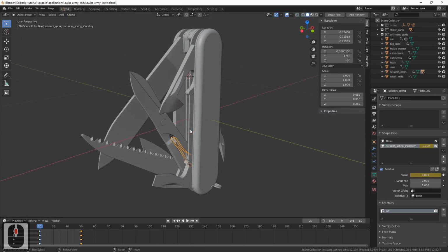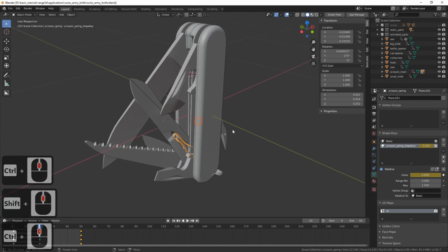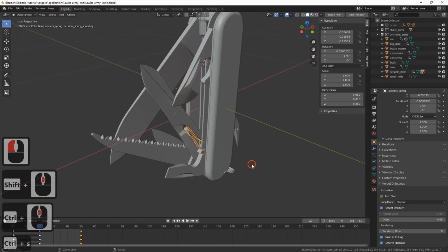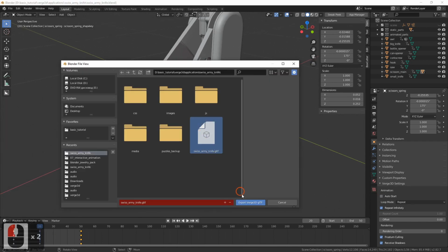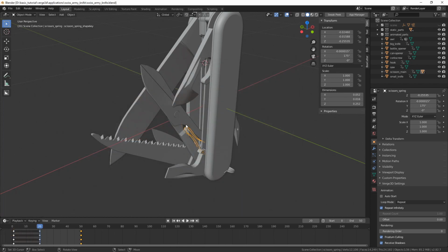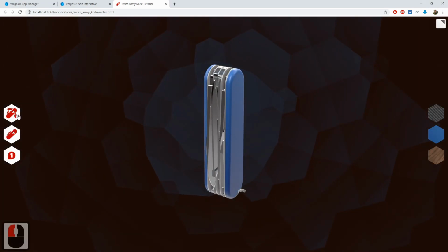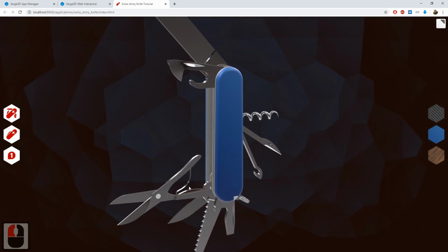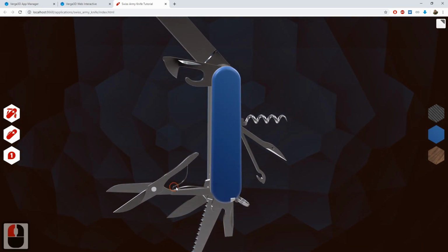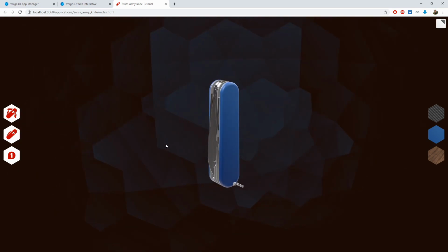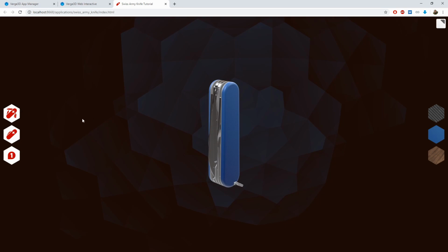This is basically it with the animation. Just make sure that Auto Start is disabled for the spring object. We can now export our scene to Verge3D. Get back to the app and refresh. Now, if we launch the animation, we can see that the spring also animates. This is because we put the spring object to the collection for animated parts. And thus, no changes are needed to make in the puzzle's scenario. It also is played back in reverse.